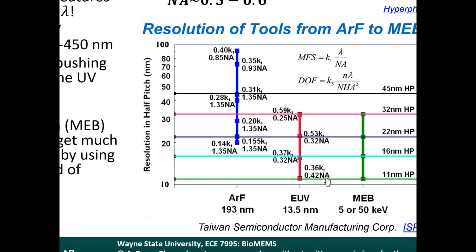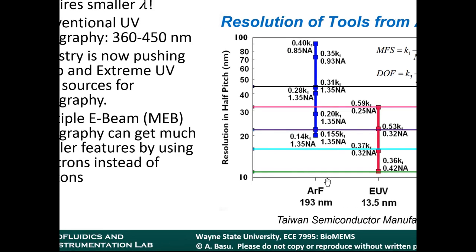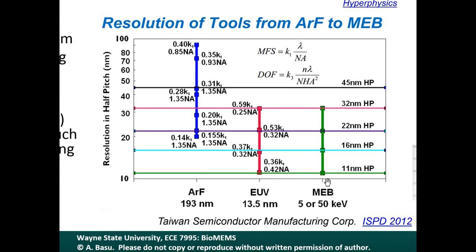Are some of those technology increases leveraging MEMS technology, like getting better lasers? Oh, are you talking about this one here? Yeah, these basically are different lasers. This laser is, I believe, argon fluorine. It's 193 nanometers, so the light source is 193 nanometers. Then extreme UV, the light source is 13.5 nanometers. So they're basically going to smaller and smaller wavelength light sources.